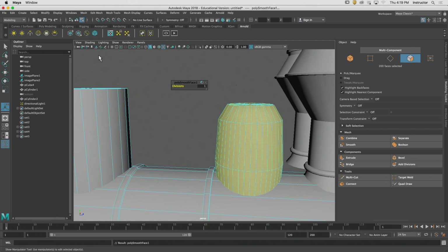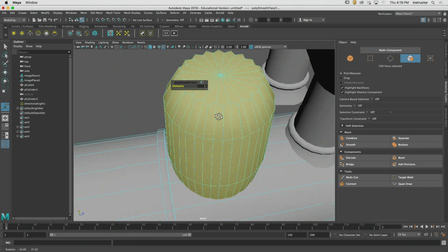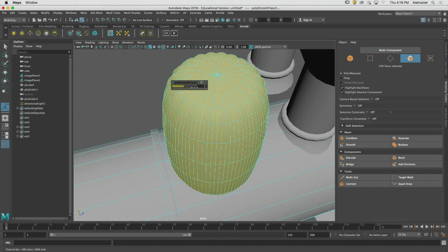See how it kind of melts it a little bit? We're physically adding more geometry, almost exponentially more geometry into the mesh itself. The edge bevel allows us to strategically put little radiuses in there. Generally speaking, there's going to be a damn good reason to use the smooth tool, because it's kind of a global operator. It's going to smooth all the polygons or whatever it is that you have selected.